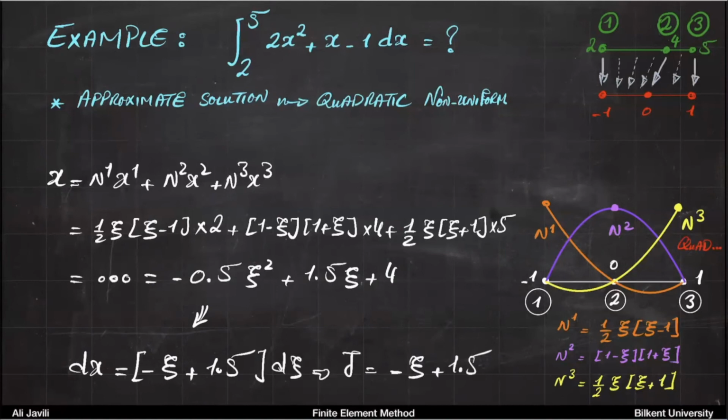Which tells you what? It tells you if c was 0, Jacobian is 1.5 like we had before. But for every other point that is not exactly in the center, that is not true, which also makes sense. So it tells you the right-hand side has more contraction, and on the left it has more extension. But at the center is 1.5, and then it changes from right to left. Okay, so this is really what you need to do.